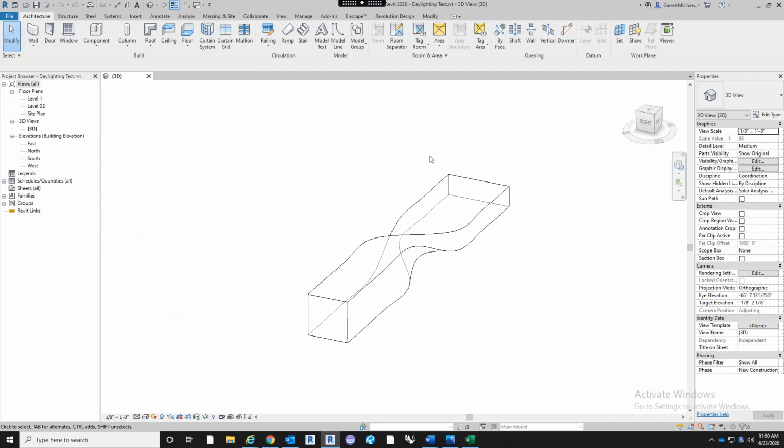So EUI, I don't know if most of you are aware what EUI is, but that is the energy use intensity. Also, more simply, it is the energy that the building has to use per square foot or per square meter, whatever you're using. And it kind of shows the sustainability of the building.